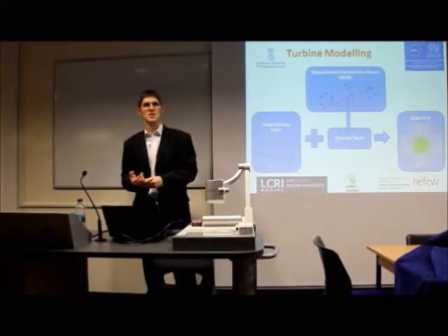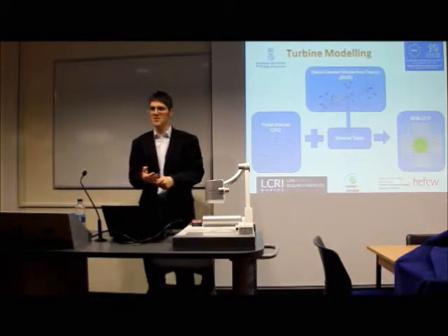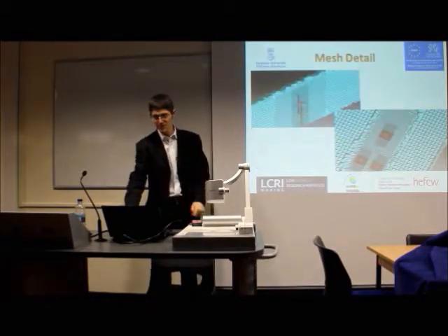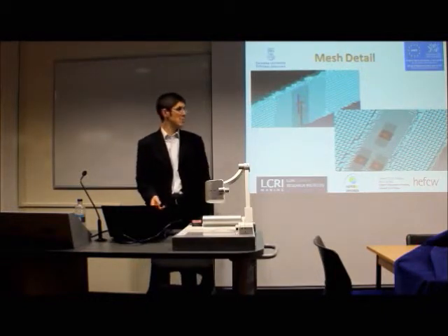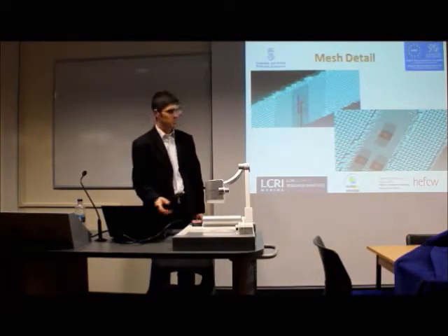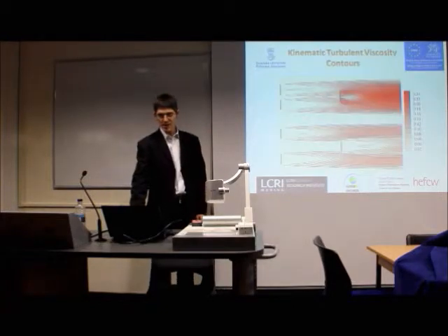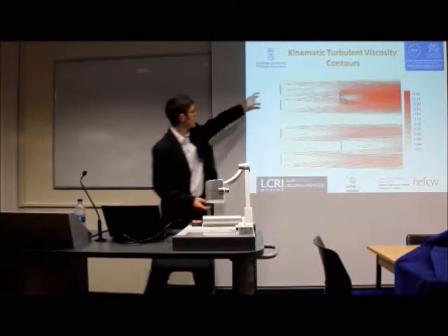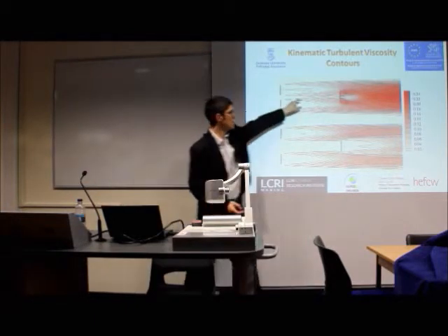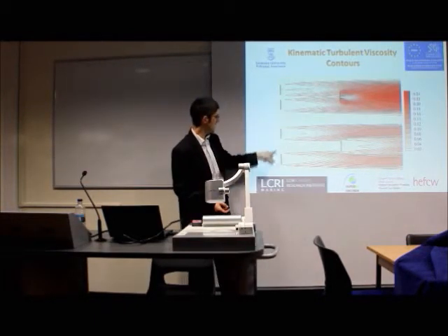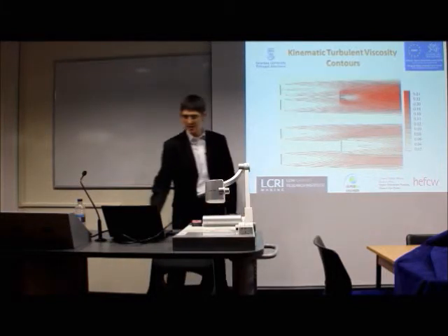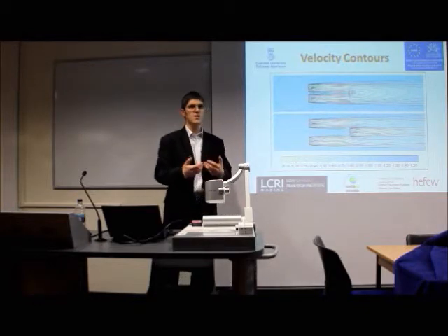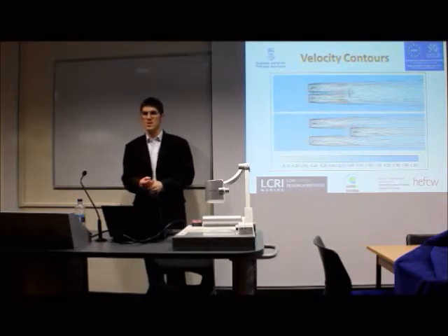In theory, you see computational fluid dynamics, or CFD, as a way of doing this model. You write a mesh, finite element mesh, looks a bit like that. This one's structured, but it doesn't have to be. And out of that we get things like turbulence for different rotors. Here the front pair are spaced quite close together, so you get lots of turbulence impact on the back one. And here they're slightly further apart. And the same for velocity, and about how those velocity fields interact with each other downstream of the rotor.